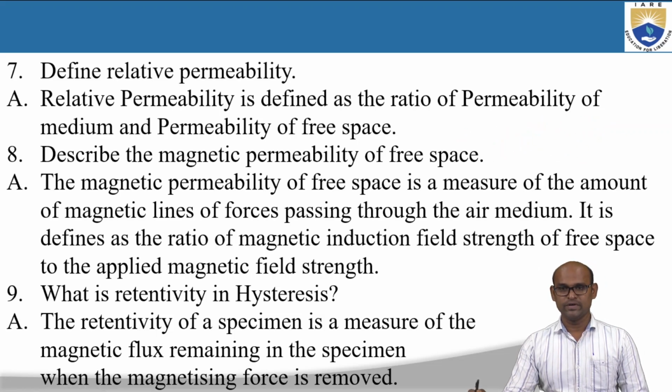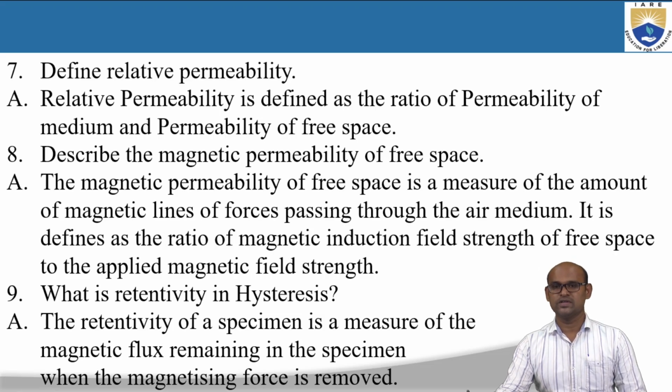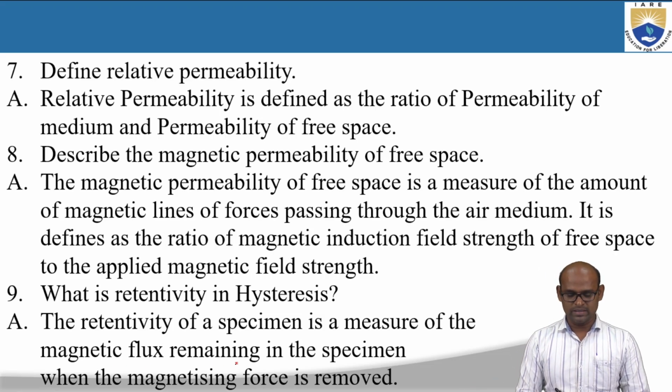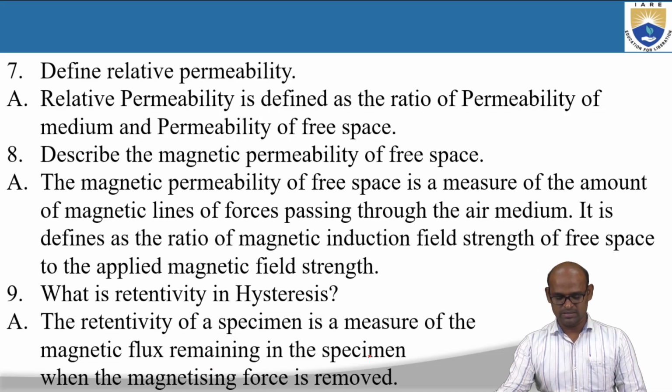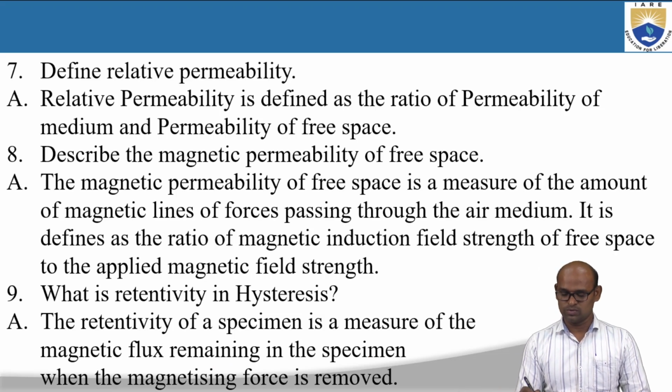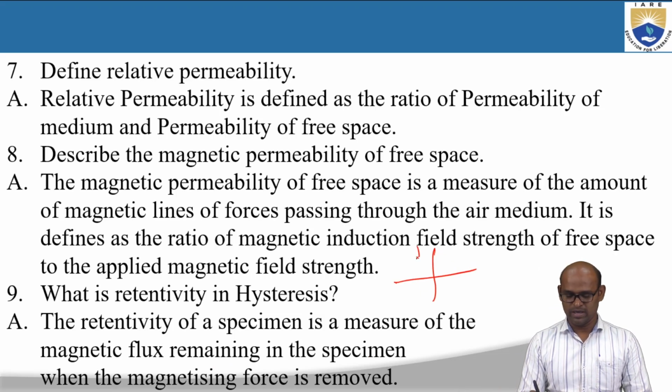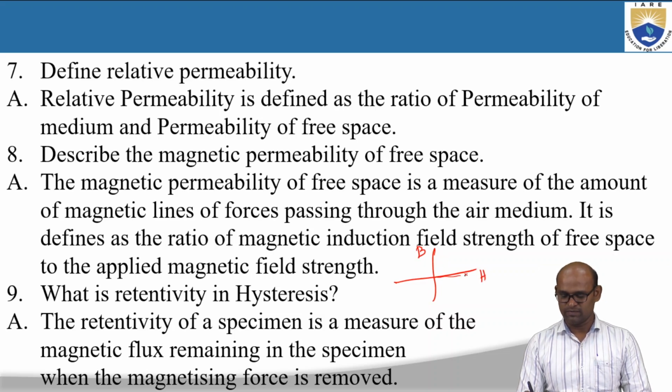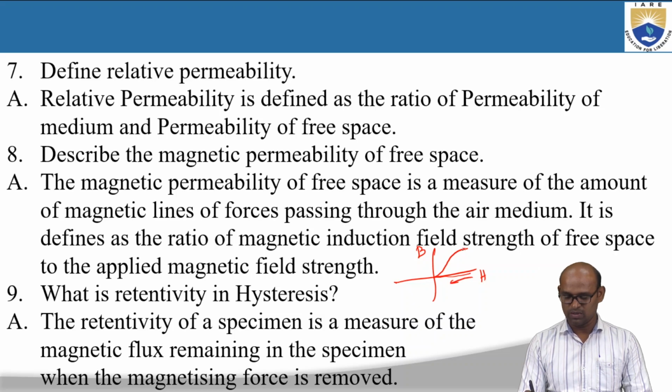What is retentivity in hysteresis? The retentivity of a specimen is a measure of the magnetic flux remaining in the specimen when the magnetizing force is removed. The BH curve, the hysteresis curve, is B versus H. As I apply a magnetic field, the magnetic induction rises and reaches saturation. As I remove the field, the magnetic induction decreases to a finite value, and the ability of the material to store this residual magnetism is called retentivity.